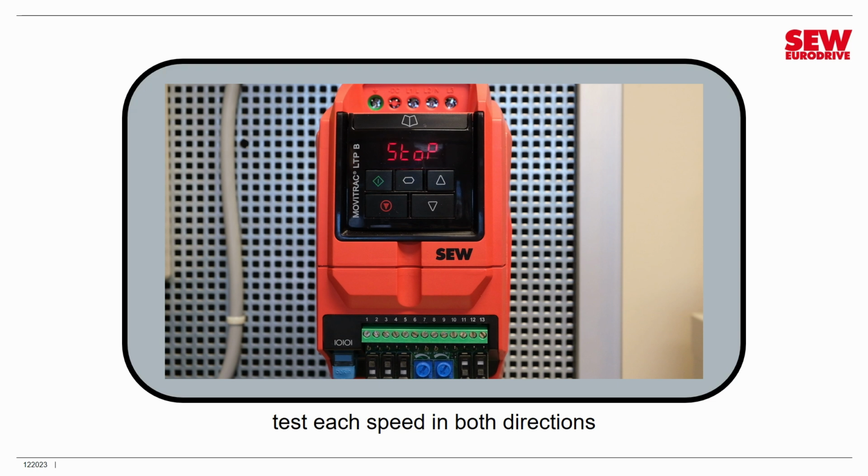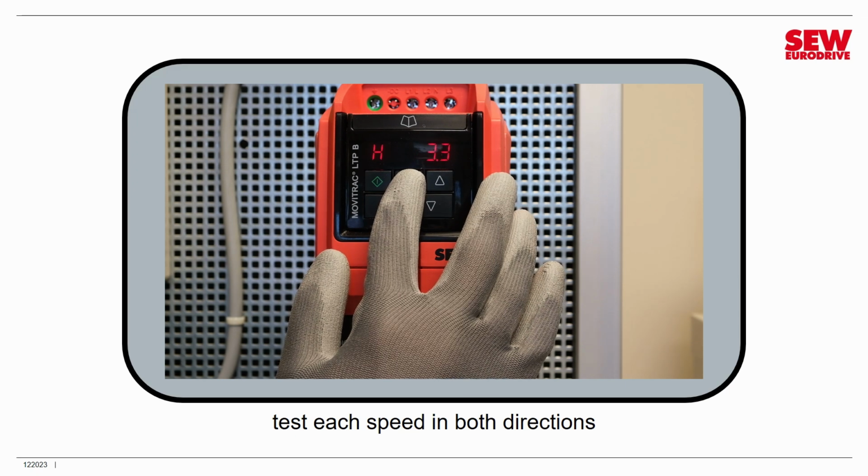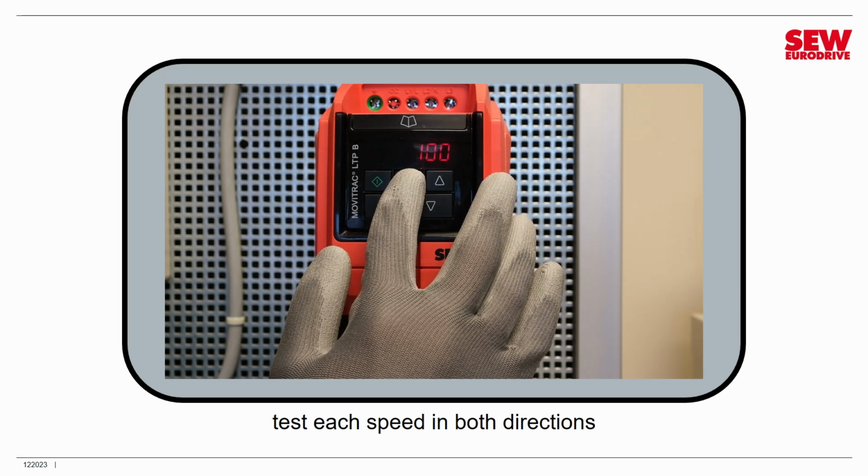I'm going to turn digital input 1 on, and as soon as that happens, we should take off at 100 RPM. Let's see if that happens. And there we go, we're at 100 RPM. By the way, if you've forgotten how to get the RPM display, remember if you press the navigate button repeatedly, it cycles through different choices, and this is the RPM display right here.